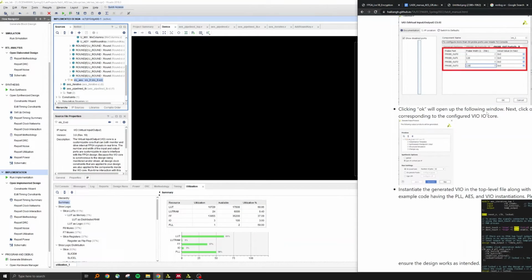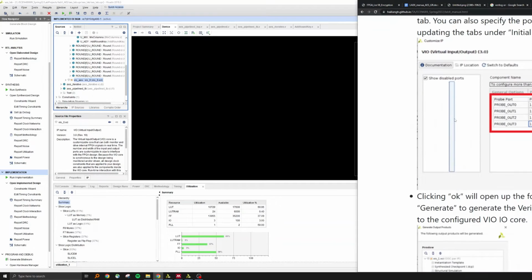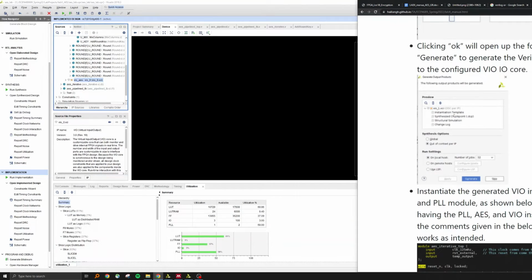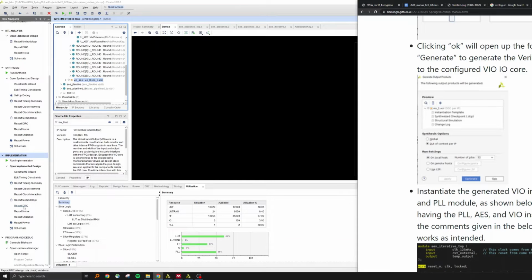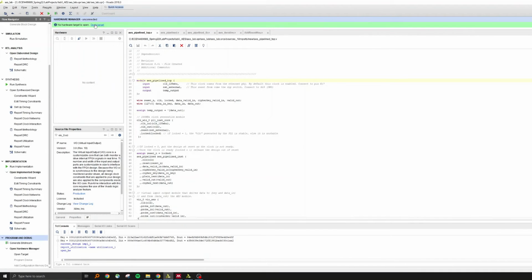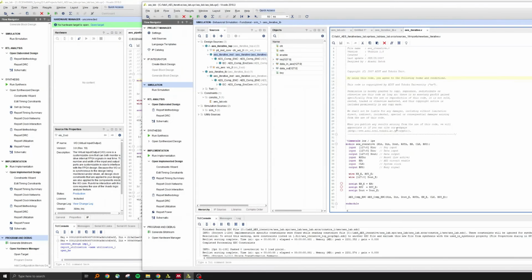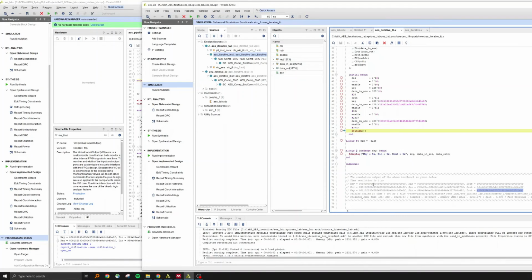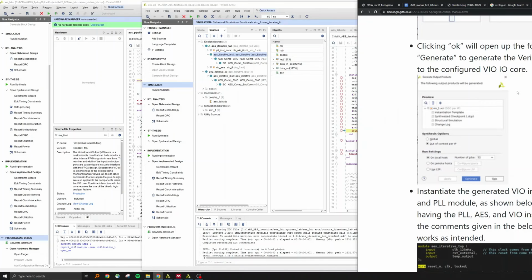And then you will download the bitstream into the board, and after that, click on Open Hardware Manager, and you can click on Open Target, and Vivado should be able to automatically detect the board connected to the computer. All right, it will just run in real time and modify some input. So I would recommend just using input here. The key and the data in are already provided for you. Just copy and paste into Vivado and run in real time.